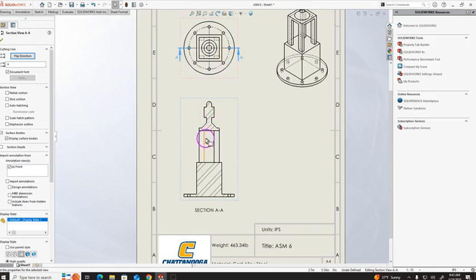And wherever the material is not cut, you can see this material has not been cut. This is the legs of this particular part. They were not cut because the location of this cutting plane or cutting line is at the center, so it is not going to cut that part. It is going to cut this upper portion and this portion only.